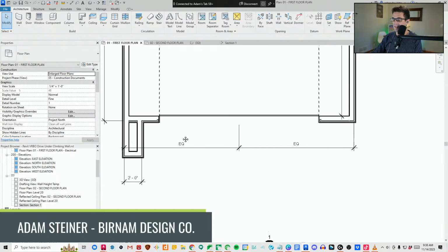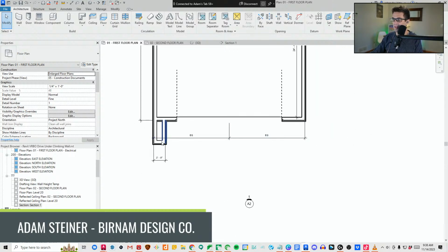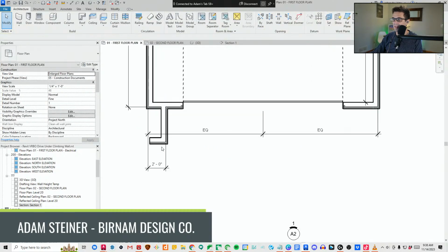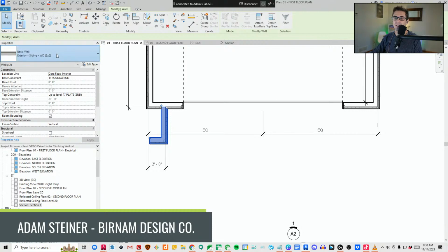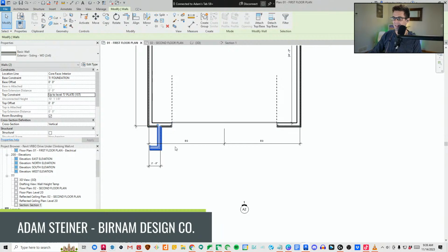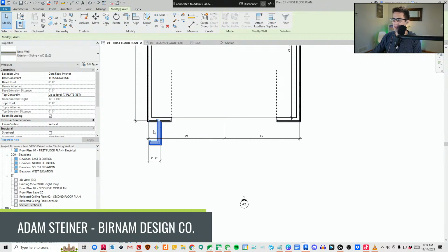Okay, I guess technically that little wall wouldn't be in there. And then this wall would stop there, because these guys are only going up to top of plate first. So I'm going to give us a little bit more space in that kitchen dining area, and do like a cantilevered overhang section that we can frame in.